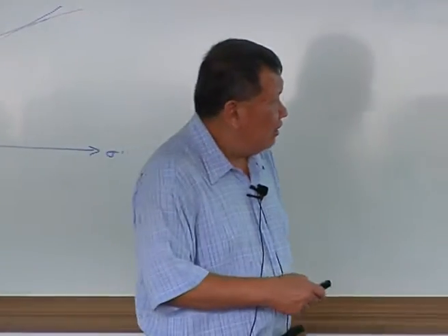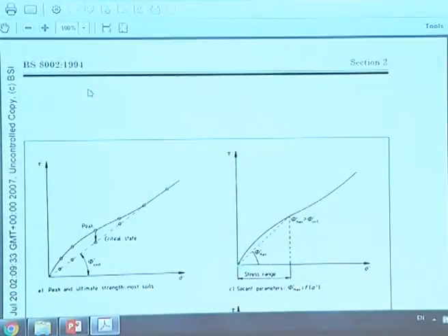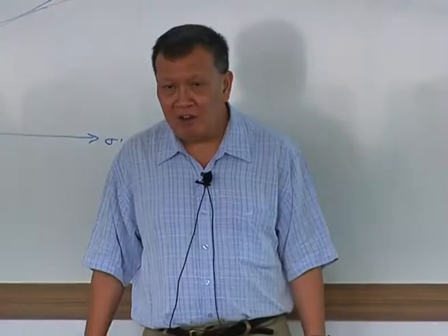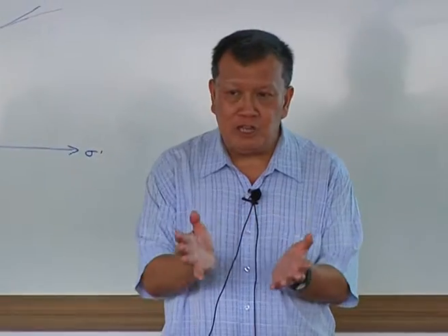And the reason why it is a curve is because, remember what we discussed yesterday and last week, this doesn't actually represent the failure envelope. This represents the Hvorslev locus of the soil. And the locus of the soil, as in the Cam clay model, is a curve. It's not a straight line. Is that alright? Okay, so basically you're just fitting a straight line to a curve. You're just forcing a curve to a straight line.